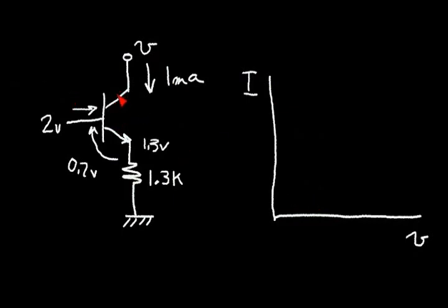Now there's a junction diode in this base collector region that I never ever want to forward bias. So this will act as a fairly decent current source as long as the forward drop on this diode does not cause conduction in this collector to base diode.